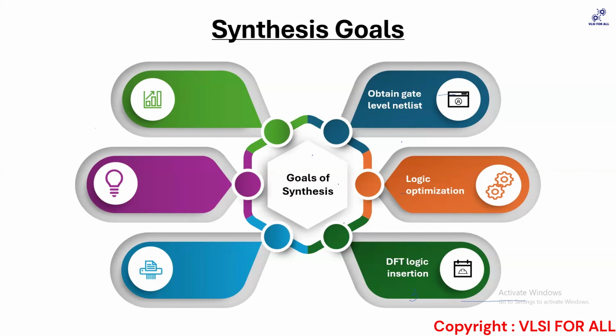So they'll explain to you that, okay, this logic, please try to make it, instead of DFF, convert it to SDF. Okay. If the scan chain reordering is done in synthesis, ma'am, then it cannot be repeated in the PNR stage. Is that right, ma'am? No. This is not such a thumb rule.